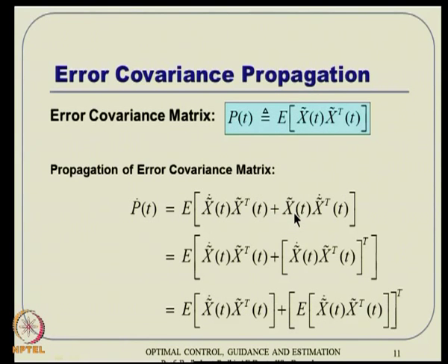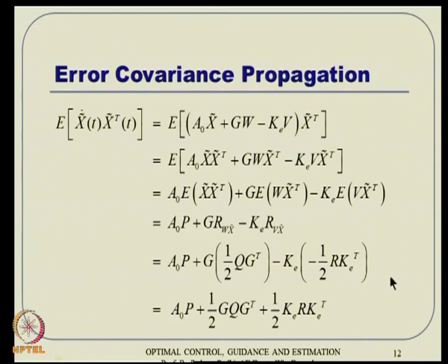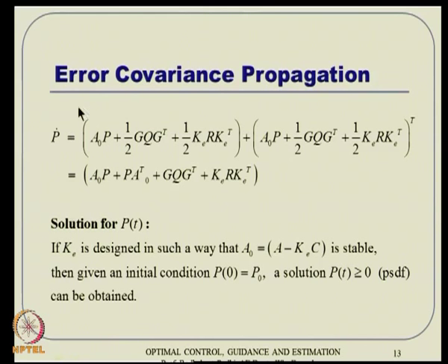Then what is p dot? Remember, p dot is expected value of this plus the same thing whole transpose. So, we got expected value of this. So, then p dot is expected value of this one plus the entire thing whole transpose actually. So, p dot turns out to be like this. So, very close to what we know in LQR theory actually.